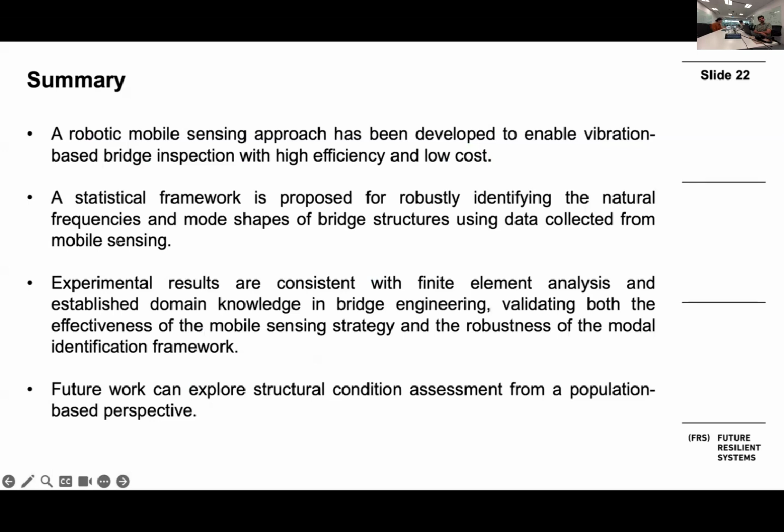So in summary, in Singapore, in our research group, we developed a robotic mobile sensing approach. It consists of both hardware solutions and algorithm solutions, and the entire solution is validated by field tests. We also proposed a statistical framework to robustly identify modal frequencies and mode shapes. And those identification results are not only verified by finite element model analysis, they are also consistent with our engineering knowledge about bridge structures. So this indicates the identification results are good.